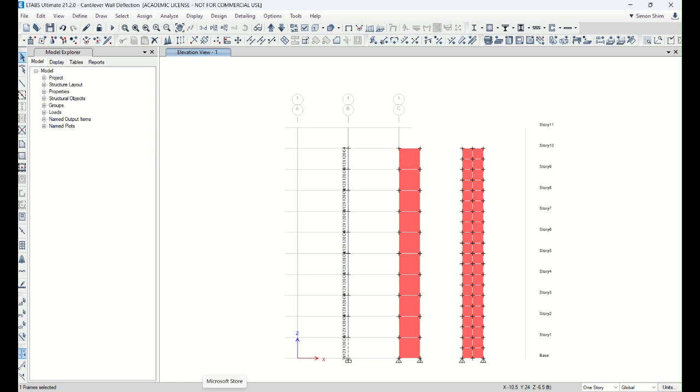But interestingly, in order to calculate the reaction and shear force diagram, moment diagram, you don't need any of these section properties. All you need is loading, boundary condition, and dimension. Right?